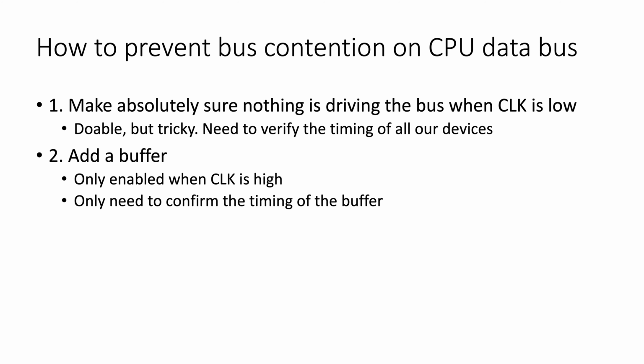And the other option is to add a buffer to the pins and make sure that the buffer is never enabled when the clock is low. And so that's the safest option. It's not strictly necessary. And maybe we'll remove it in a future video in order to simplify the circuit once we're more confident in our bus management. But for now, let's build it.